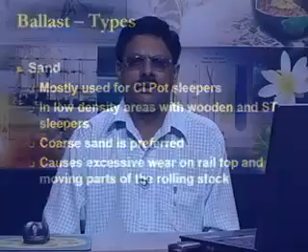As we have seen when we discussed the wear of rail sections, with respect to the position of the wear, sand particles may get attached to the top surface of the rail sections, and when the rolling stock moves over that section, there is a grinding effect of this material, and because of that, corrugations may get induced into the rail section.